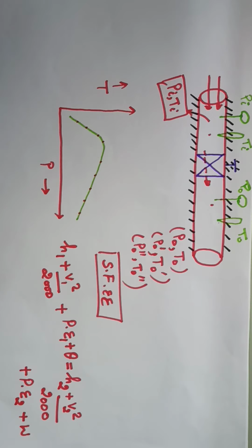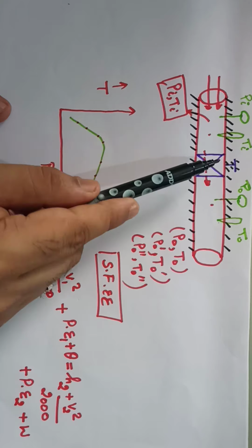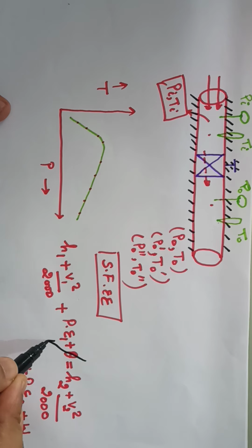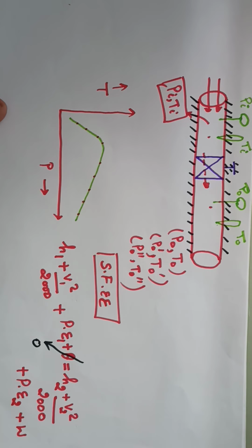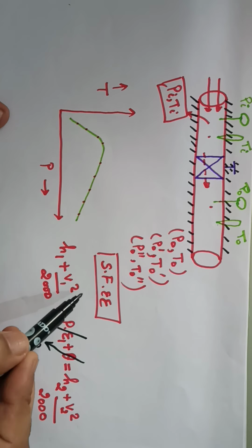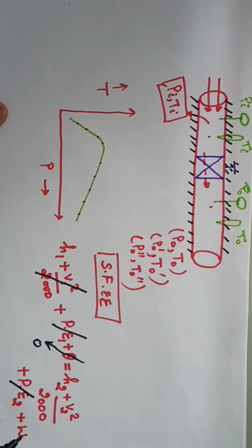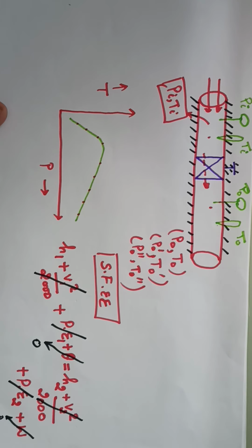First, we have made the system insulated so that no heat transfer occurs across the system. So I can say that this is 0. This is a horizontal system, as we can see, so we can also neglect the potential energy. Now there will be a very small change in the kinetic energy of the system. There will be very small change in the velocity of the gas as it goes across the wall. So we can also neglect the kinetic energy, and also for this system no form of work done can be seen here.